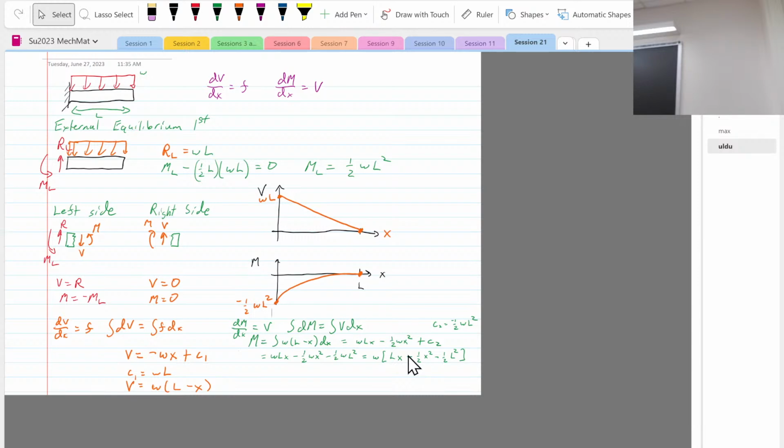And then you add up the ones that are on the same axis. Meaning, let's say I have two moments on the same axis, you just add them together? No. In this case, that's fine if it turns out they're the same, but I look at each load separately, so be very careful about adding stresses to each other.